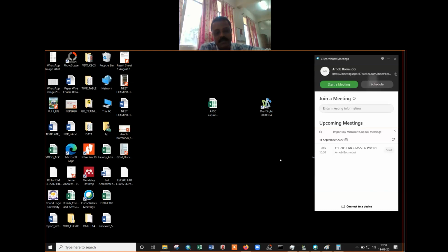In order to draw a line, you have to type L. In order to draw a circle, you have to type C. In order to draw a rectangle, you have to type REC. So these are the things. In order to trim, you will have to type TR. Or you can play with the software, and then you can find by yourself where these things are.